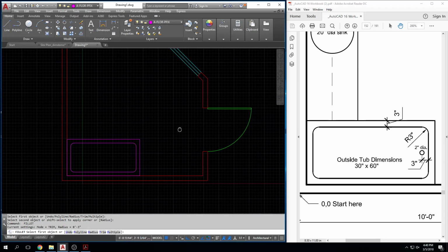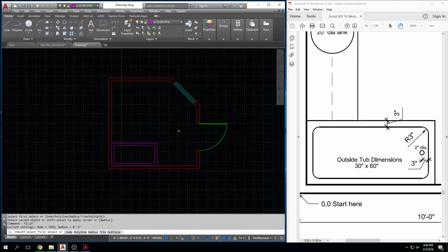Okay. A couple of things that I do in AutoCAD. I do things all at the same time, meaning if I need to fillet a few things and they all have the same radius, I fillet them all at the same time and continue until I'm done. And I hit enter in between, right? I don't escape and redefine a command to start it over, because that involves stopping, hitting escape, reinitiating the command, defining it, and continuing on. So you'll see me F for fillet, R for radius, enter, and then I'll do all the filleting that needs to be done, and I hit escape.